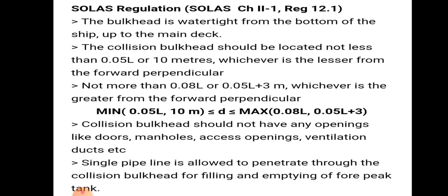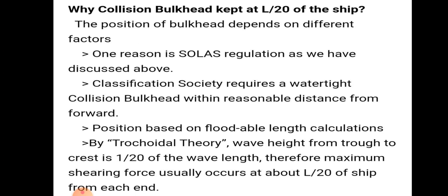The collision bulkhead should not have any openings like doors, manholes, access openings, ventilation ducts, etc. A single pipeline is allowed to penetrate through the collision bulkhead for filling and emptying the forepeak tank.